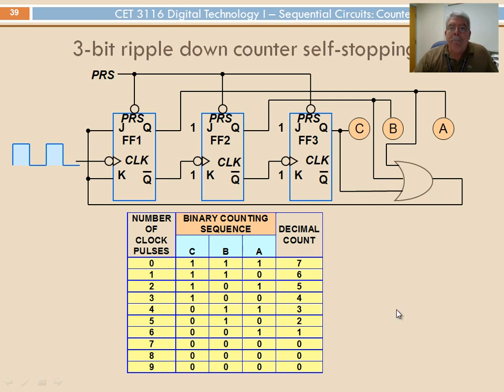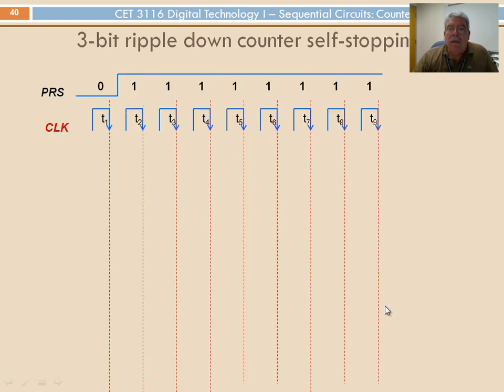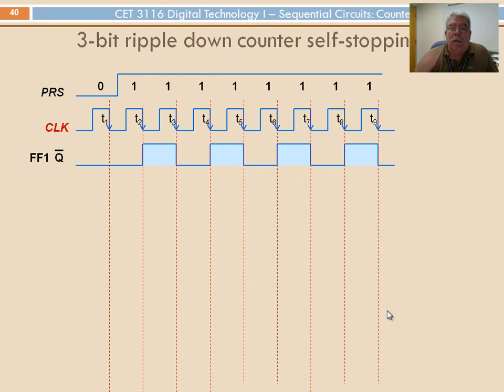All right? So here's the graphic for the flip-flop. Essentially, it's a 3-bit down counter in which we initially do a preset. With the preset, in this case, we force a 1. This is the clock, as usual.